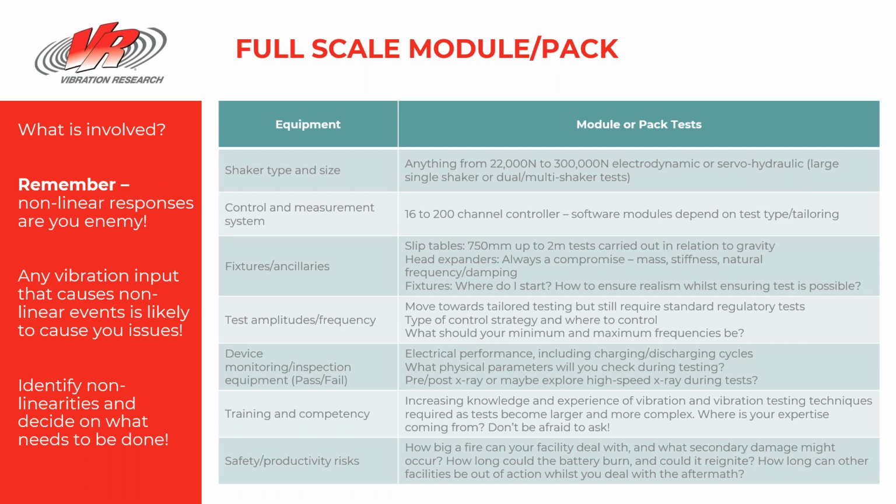The whole interaction between the test facility and the battery pack really starts coming into play, and looking at how you're going to control the test. Looking at cross-axis, am I damaging the shaker systems? People are looking at multi and dual shaker systems for doing this, and you can do a lot of damage if you don't know what you're doing with multi-shaker tests and how they're controlled.